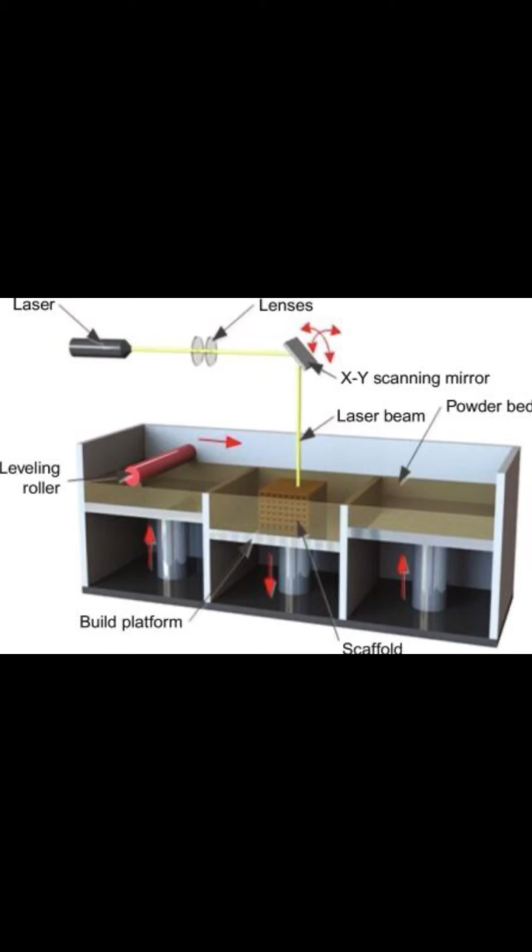For each layer, a heat source scan path is calculated, which defines both the boundary contour and some form of fill sequence, often a raster pattern since the heat source is typically an energy beam.